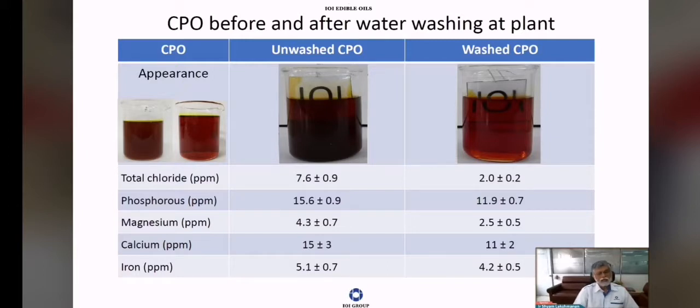And we analyzed that further to see what other substances are being removed. If you look at the table at the bottom, you'll see we analyzed chloride, phosphorus, magnesium, calcium, iron, zinc, tin as well, right? And you'll see that all of them actually reduce. Now, all of this actually imparts greater oil quality as well as greater stability of the oil. There are also research papers that have identified that substances like iron, zinc, and stannum do catalyze the formation of MCPDE. So its removal is actually encouraged.